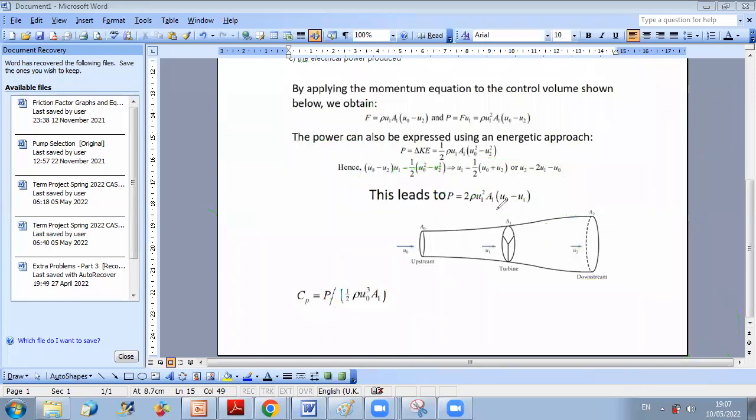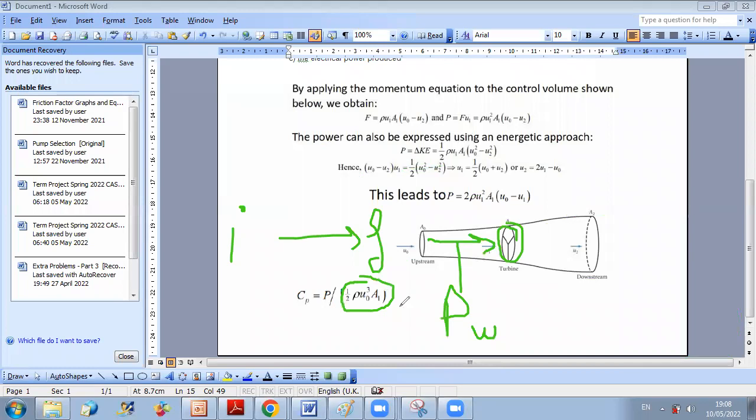Okay. Look, let us go from initial to final state. You have wind crossing your system. This wind crossing your area here contains a certain power of wind. You can say that the power of a flow over a certain area is calculated through half rho U0 cube A1. So this was demonstrated in the course. So this is the total initial power that you have, but you are not able to use it completely. Why? If you have 100% efficiency of your system, this is the power you will have. But your system is not 100% efficient.